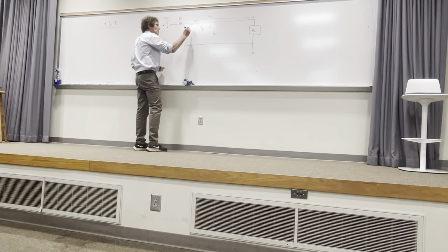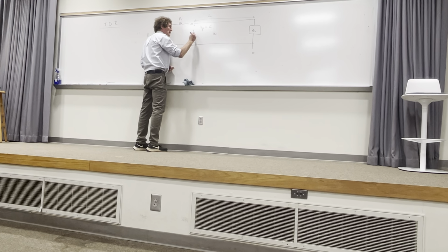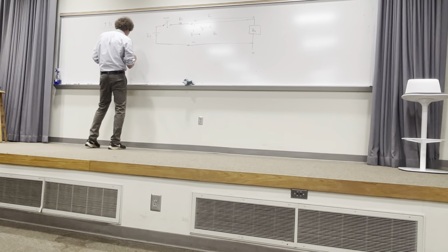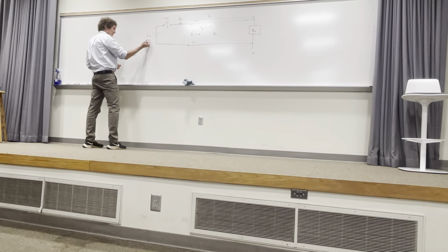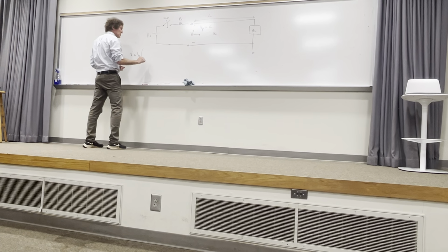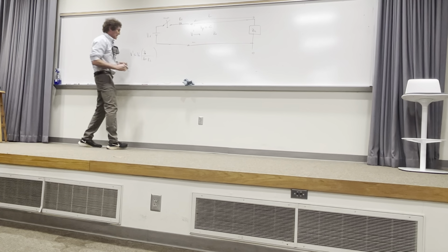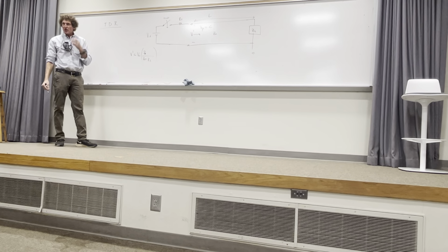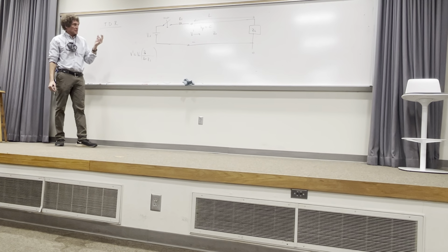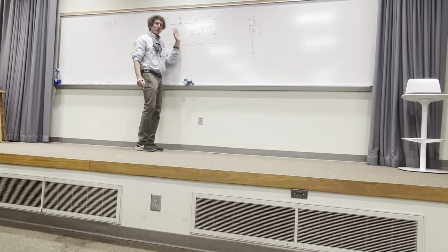So there's going to be a voltage pulse developed that we call V prime that's going to propagate that way. But V prime you find equal to this voltage, and it's just found using voltage division: Z naught over Z naught plus RS. Now that should make logical sense. If we talk about voltage division of any two resistors, you take the source voltage that's across both, multiply it by the resistor you want the voltage across, and then divide by the sum of the two resistors. Should make logical sense.